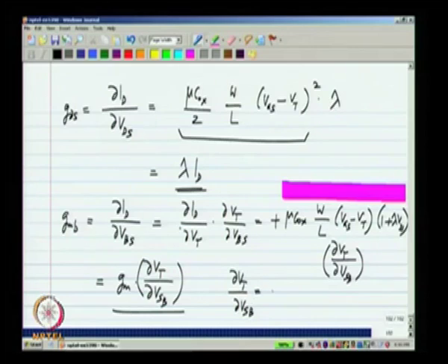So, it is something proportional to GM, and this ∂Vt/∂VSB is a number that could be of the order of, let us say, half to 1/4 or maybe slightly smaller. It is not a very small number, nor is it more than 1, it is typically less than 1, but maybe between half and 1/4 or something like that. Okay. So, this GMB, the transconductance from the back gate or the bulk, can be a significant fraction of GM.